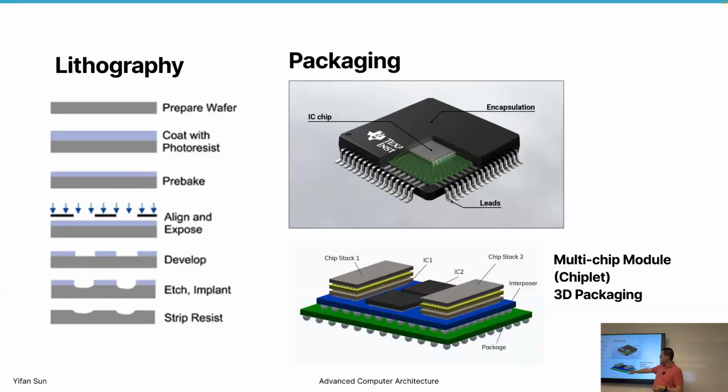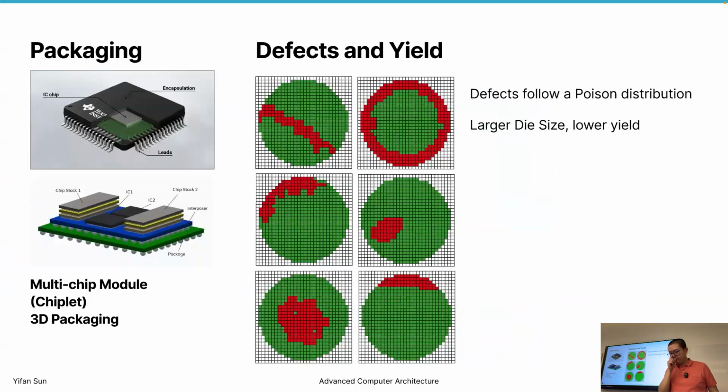But as you can see, the interposer is a piece of silicon. What's the largest size of a silicon? It depends on the wafer, right? The wafer is the maximum size of a silicon, because that's the piece that we can slice. So system on wafer is probably the largest that we can imagine on this type of technology that's expected to deliver high performance communication between chips. Probably we can see super expensive devices coming out in 2027 or 2028.